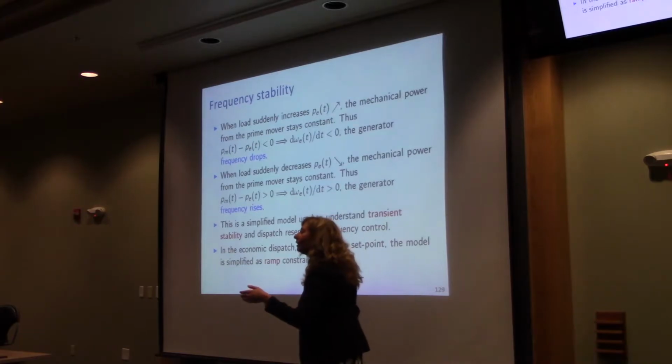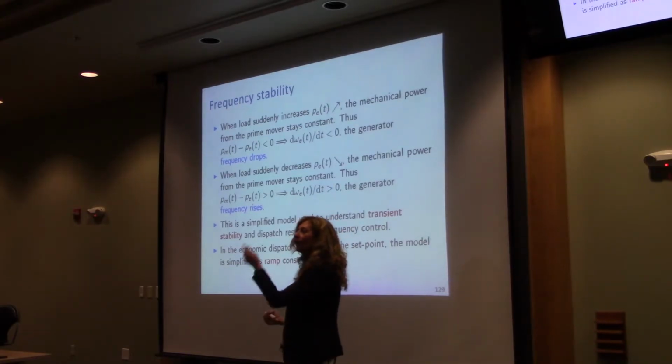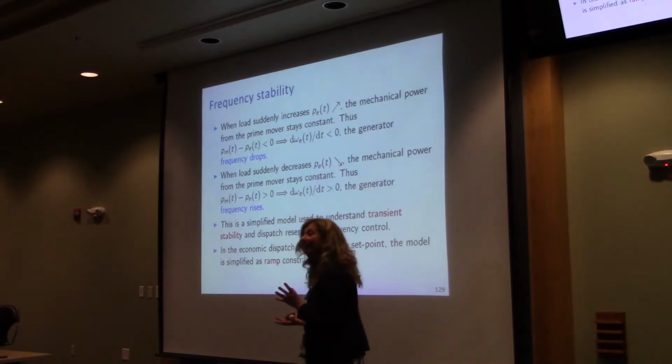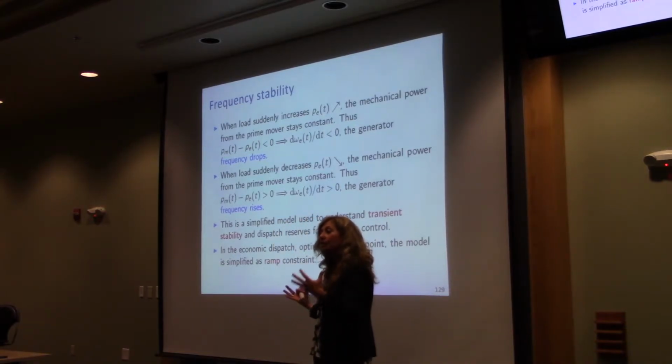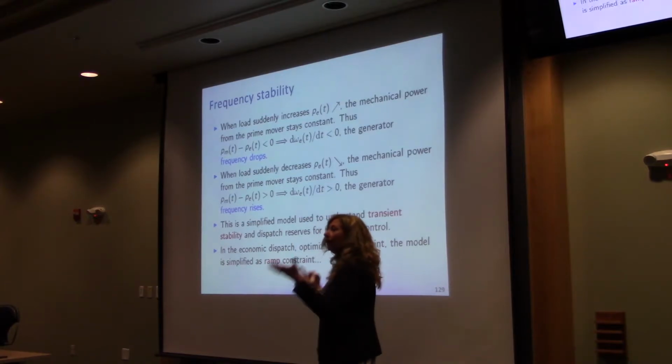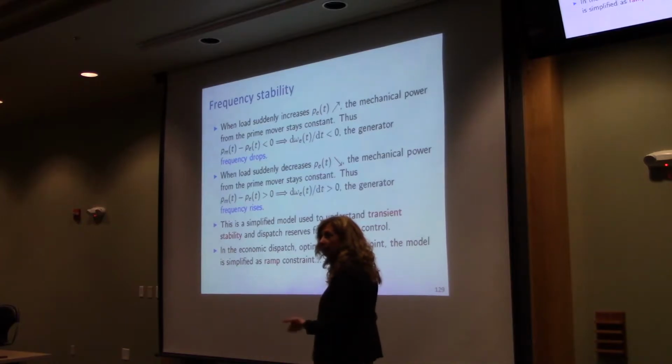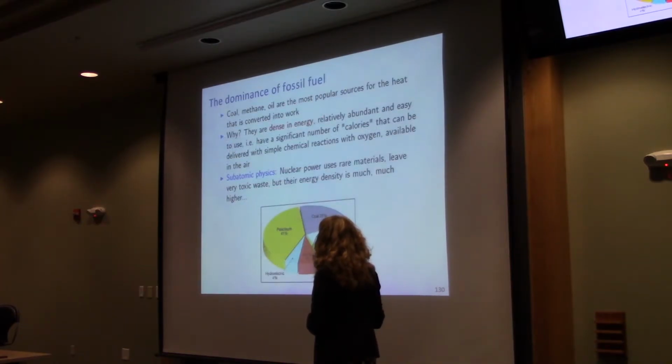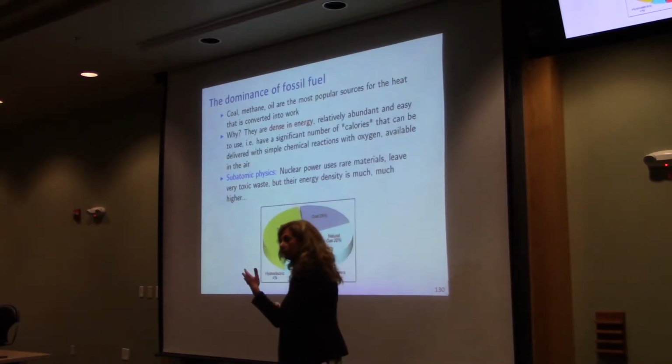Okay? So people think that blackouts is because a squirrel cut a line and then the line caused everything. It's actually not like that, right? Oftentimes it's because these systems cannot resynchronize and go around a stable point and create these strange oscillations of power that eventually take them off the network because of safety limits and cause these cascading failures, okay?